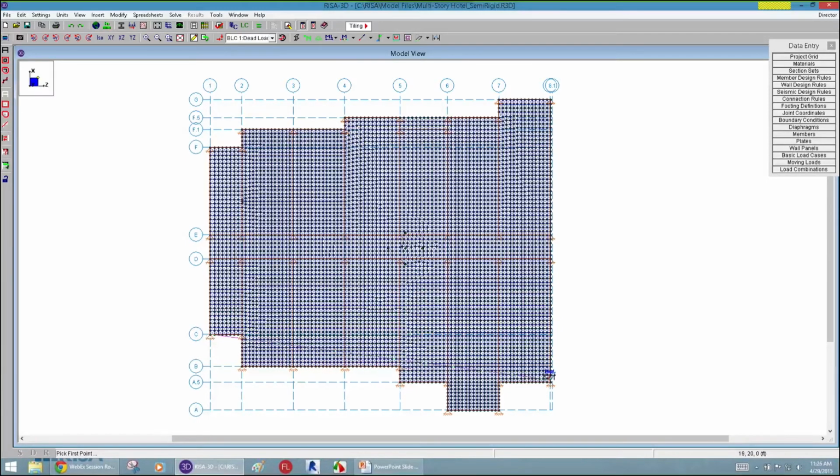I'm going to apply it to this face here, and that's going to be looks like 86 feet across this face. And I'm going to find the value I need to apply per node. So I have a number of nodes I want to apply at the face. That would come out to be about 47 pounds per node there.